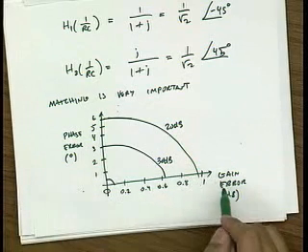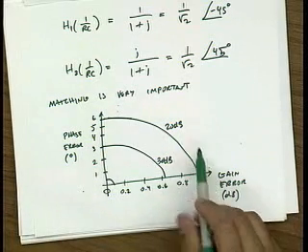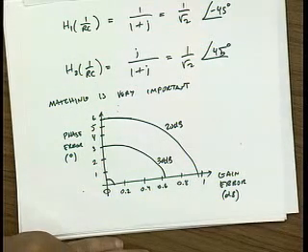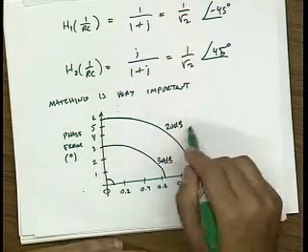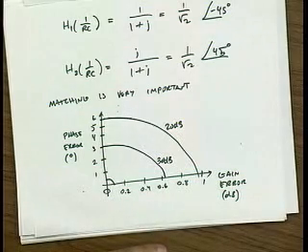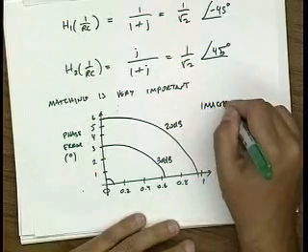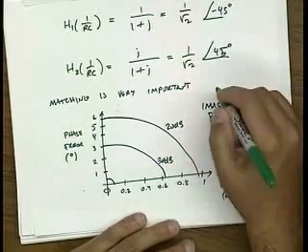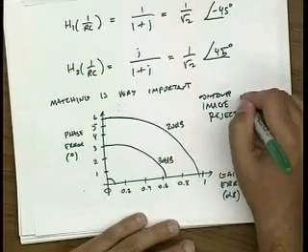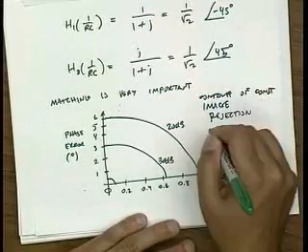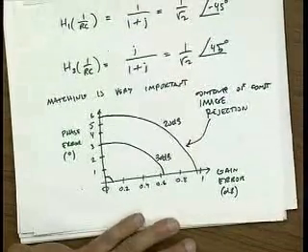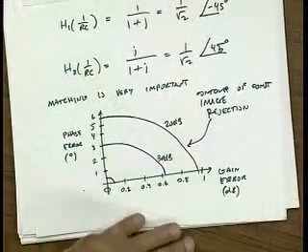If you have more and more gain error, you get less rejection. So 20 dB means I'm rejecting my image by only 20 dB. So this is the image rejection. So this is a contour of constant image rejection. Sorry, these pens are hard to write with.